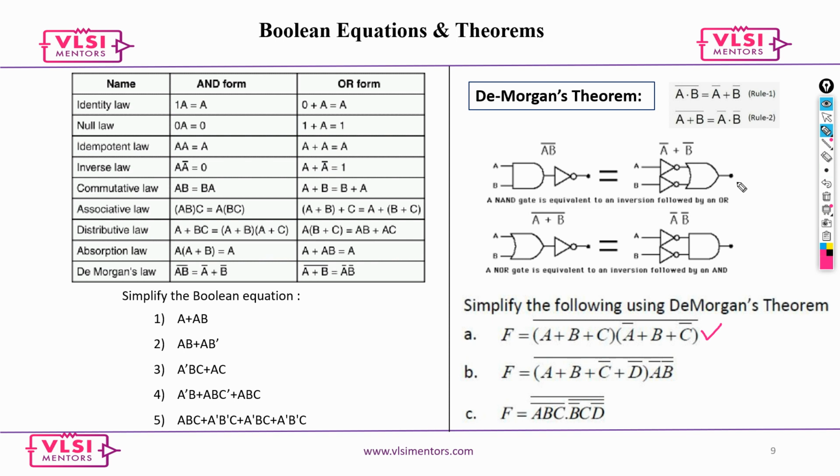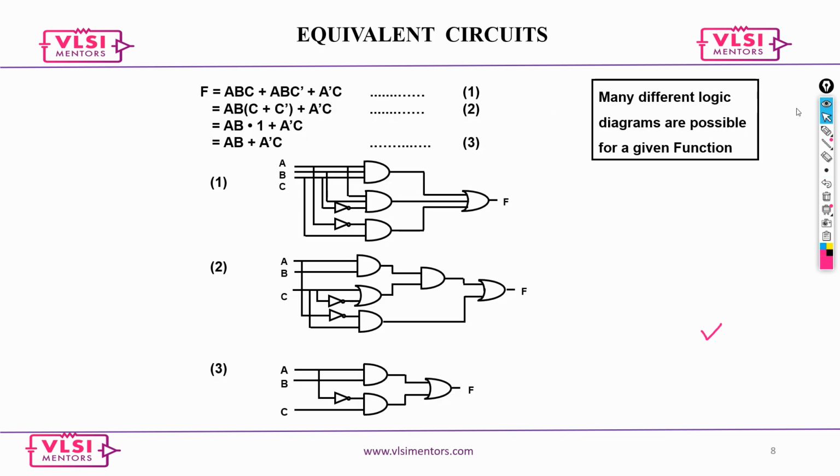Yes, optimization means reducing gates, right? Yeah. It is not only reducing gates. It is basically optimizing your whole delay from start to end, and you might be reducing your area, downsizing the cells, or choosing different types of VT flavors. You see here, these three are equivalent circuits.